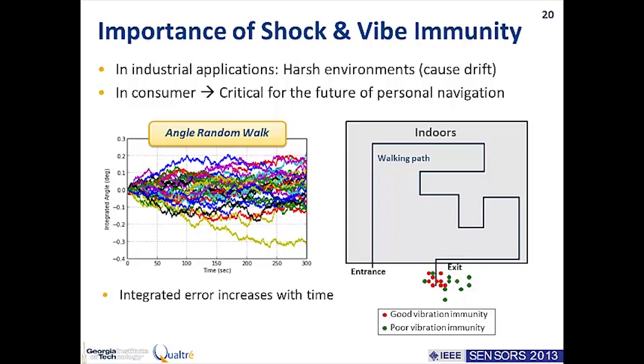In some tuning fork type devices, sometimes you have your anchors on the outside of the sensor, so any stress differences between the corners of the device are going to transfer directly into your sensor. So what people most of the time have to do is come up with decoupling structures to avoid this kind of problem. In the case of this disk resonator, since they're sensor supported, there's a lot less difference in the stress that is going into your device. So that's obviously a good advantage in terms of vibration and stress immunity.